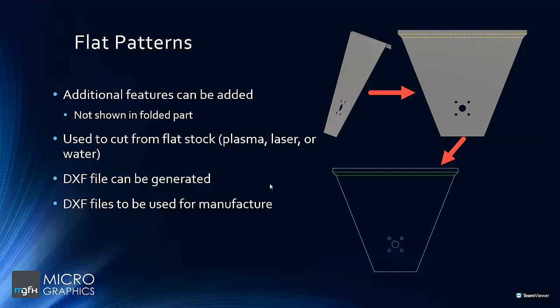So you're able to do your complete round trip from design, to creating flat patterns, to creating your CNC program and post-processing that out to your machine, all within Fusion 360. Alternatively, if you have an external supplier that does your cutting and bending for you, you can generate a DXF file and send this on to that supplier so that they can manufacture.